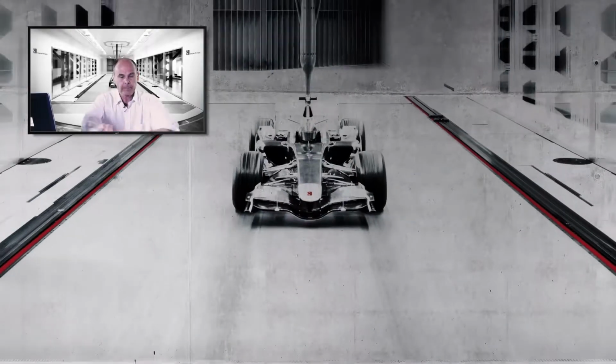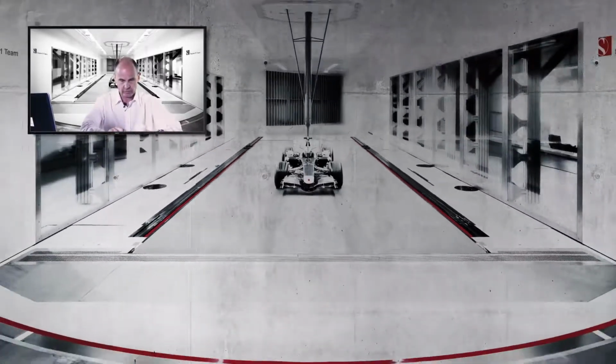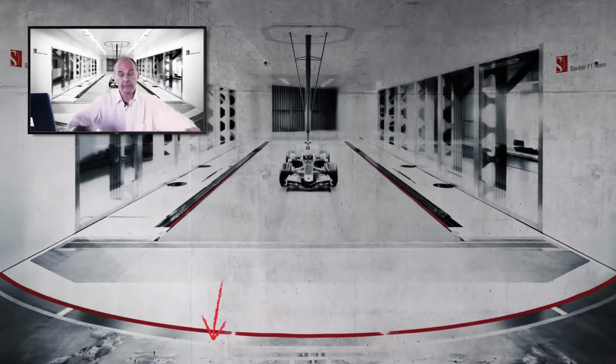There are lots of ways, but a simple way would be to create a step, if you like, near the leading edge of the working section and suck off, at exactly the right speed, any air that is moving more slowly than the air in the free stream.